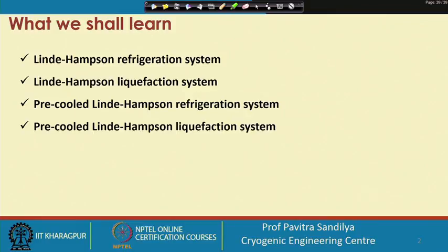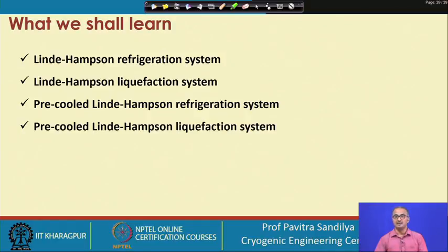We have taken these methods in pairs because we will find that the basic cycle remains the same whether we are going for liquefaction or refrigeration. The only thing is, as we have learnt earlier, that refrigeration is a closed cycle with a balanced flow, while liquefaction is an unbalanced flow situation and an open cycle. So, only that differs, but otherwise the basic cycle remains the same.